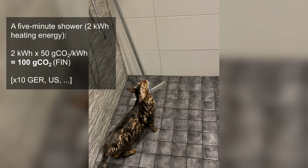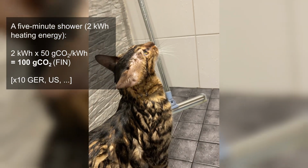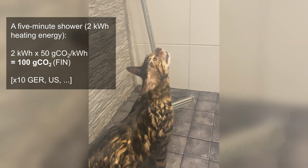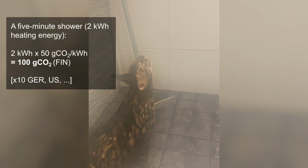But this changes if the water is heated. A 5-minute shower needs approximately 2 kilowatt hours of energy. That might be district heating, that might be electricity. And the emission is in the ballpark of 100 grams of carbon dioxide with Finnish energy, be it district heating or electricity, but it could be double that, closer to a kilogram with, say, German energy. So the carbon footprint of the shower water in Turku would be around 10 grams of carbon dioxide, so it's not very significant, it's close to zero, but heating is the important thing.